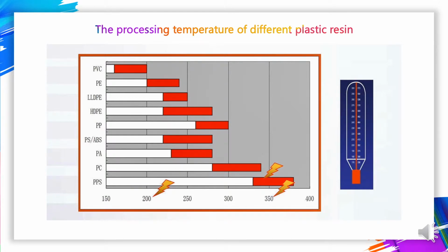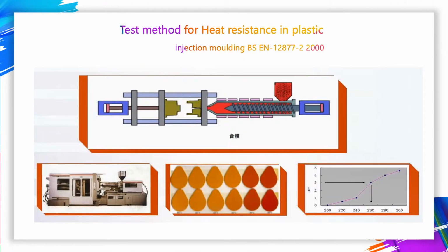Normally, the heat resistance of inorganic pigments is excellent. The organic pigments and dyes are much lower. Therefore, it is very important to choose suitable colorants through the heat resistance index. At present, many colorant suppliers test the heat resistance of each pigment in different plastic resins according to the method of EU standard 12877-2, so as to provide reference for customers.